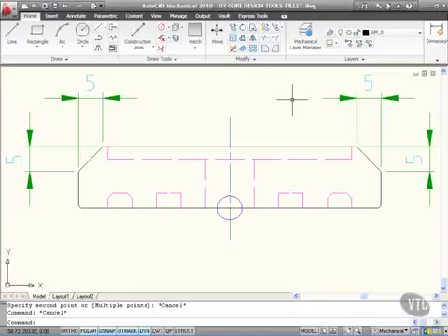Our next core design tool to look at is the fillet core design tool. Very similar to chamfer, but what you're doing is instead of applying a distance, you're applying a radius. Now this curved groove here hasn't got a curve yet. It needs a curve on that corner, a radius. Now the distance from there to there needs to be measured. So let's measure that first.